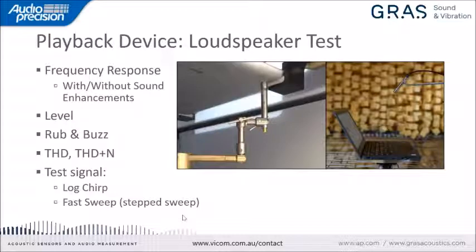There are multiple parameters that we can measure when doing acoustical tests of the internal loudspeakers of a tablet or a laptop. First of all, of course, the frequency response, which is typically considered the single most important aspect of the performance of any audio device, and this is no exception. We can measure the frequency response of the laptop and tablet loudspeakers with and without the different sound enhancements at different levels. So we can test, for example, the linearity of the speakers at different SPLs. We can, of course, measure the level generated by the speakers